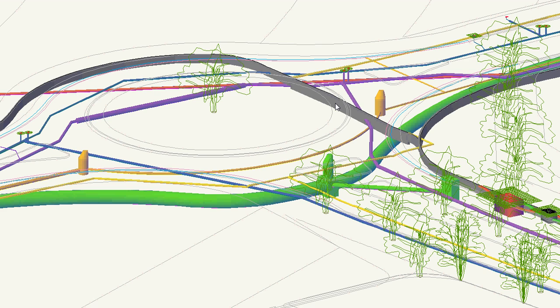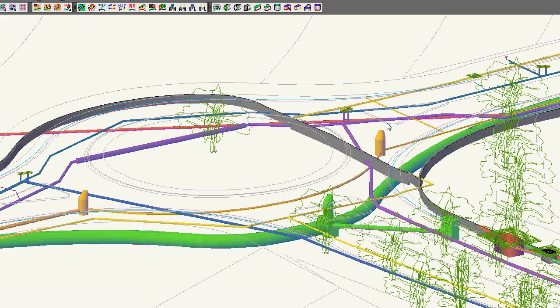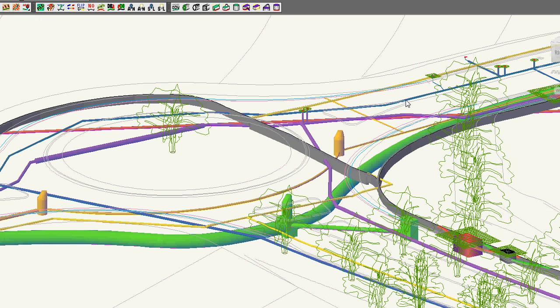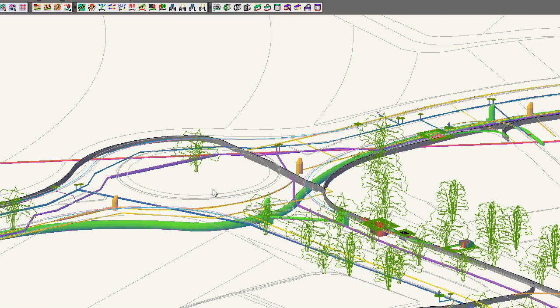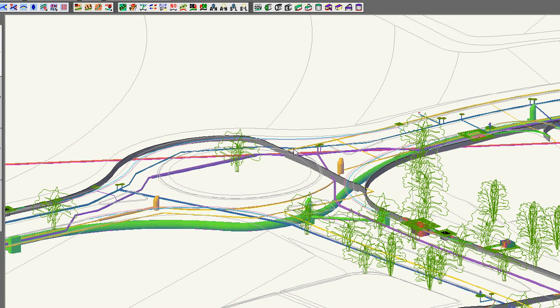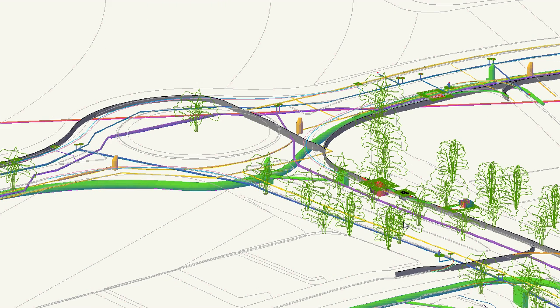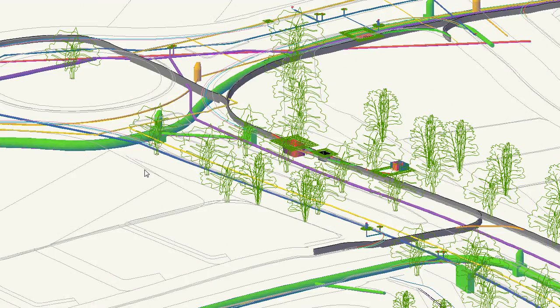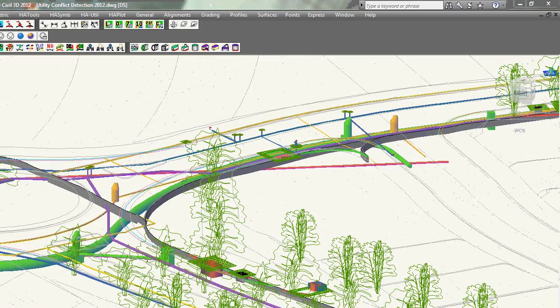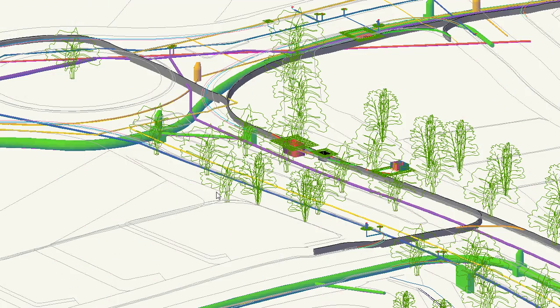You can enter those elevations and explain to the computer what's going on with the 2D feature, where the elevations are along it, and it interpolates in between, and then you apply sections and it moves those around, and as anything updates, you just update the information and it updates the 3D line work. That's how our tools are set up. It's a bit different than how, let's say, Autodesk corridors do things, but we found it to be really efficient, and we use it in production. So let me go over to some other areas here.